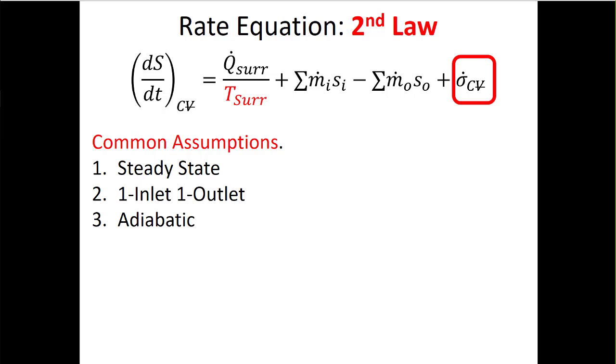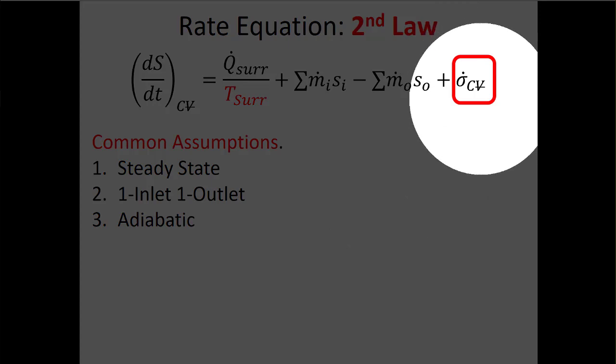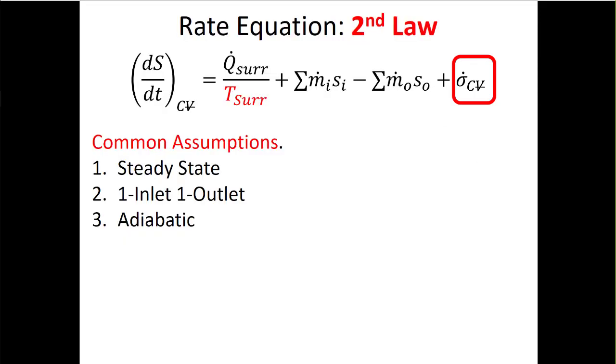In that case, you'd have to do a second law analysis. So we would write down the second law, and because the system is a series of open components, we would use the open version of the second law, and we'd be trying to find the sign of this sigma dot term. That's if it's just asking. If you get a multiple choice question on the exam that says, is this thing possible, you might not actually have to do the math, because maybe you can isolate an equation for sigma dot and find out that all the terms in the equation are positive. If that's the case, then it's positive. But if the problem asks you what's the entropy generation rate, then you'll have to fix the states.